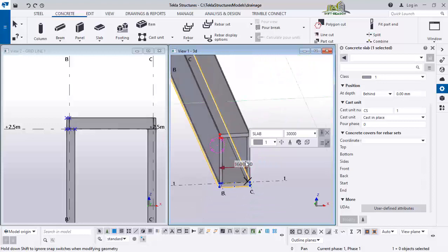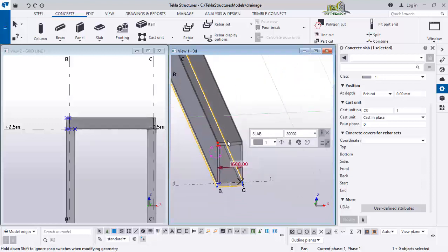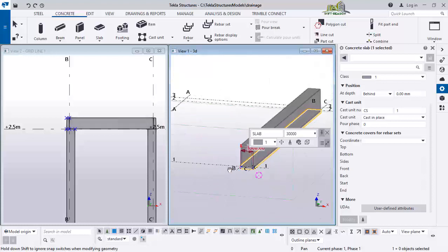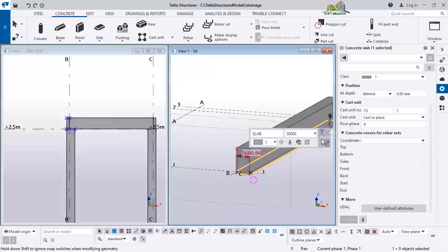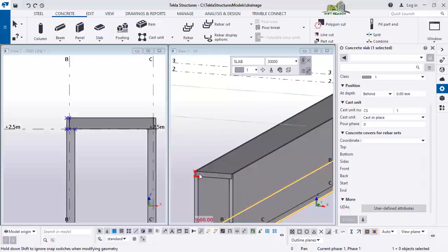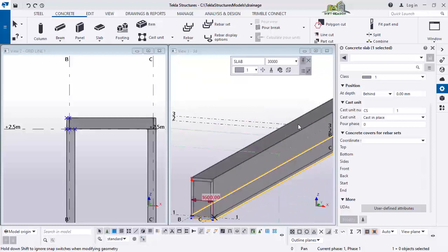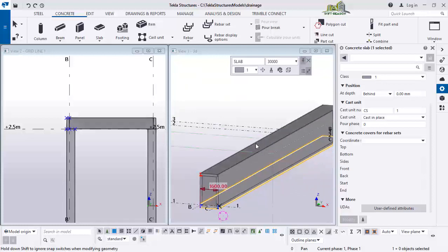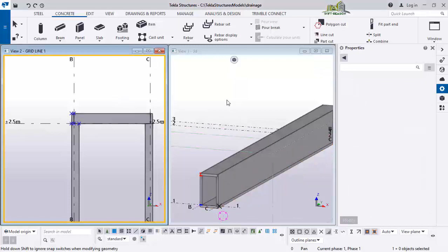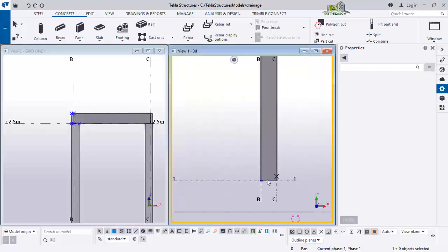Okay, so the next thing we will be looking at is how to create a opening for inspection. Okay, inside of the drain, opening for inspection, we will be having inspection of a length of spaces 6 meter. Okay, so I will do Control P to go to the plan view.